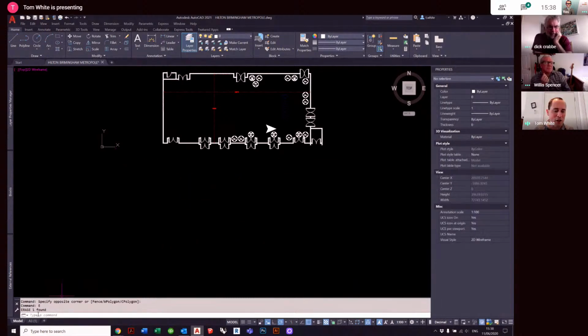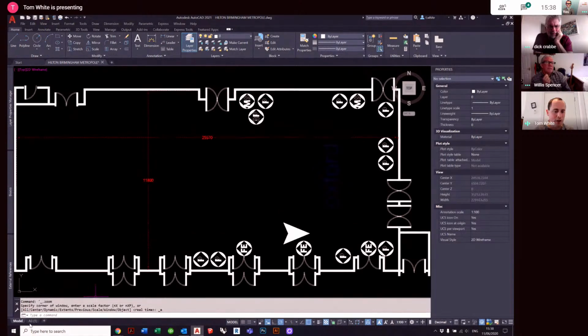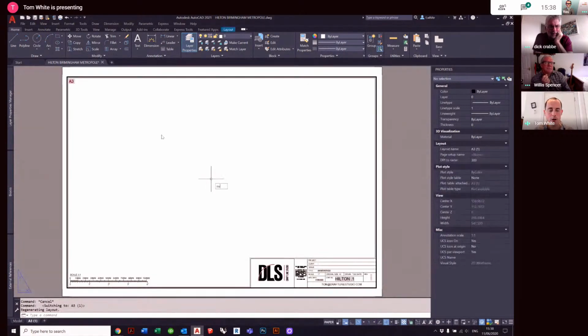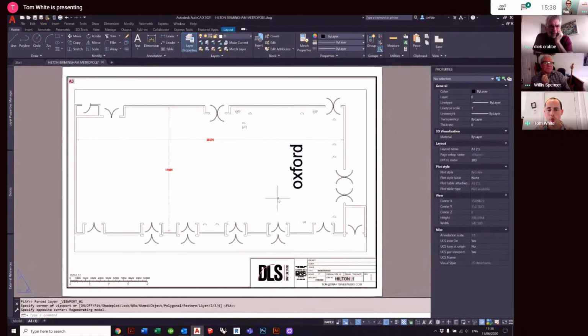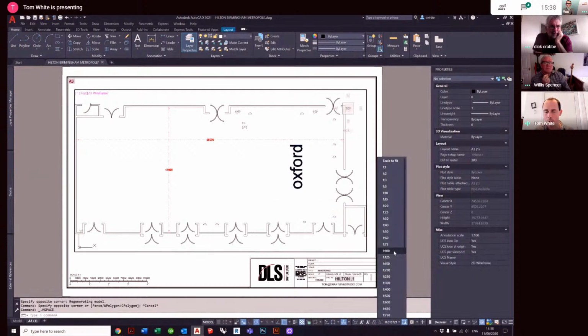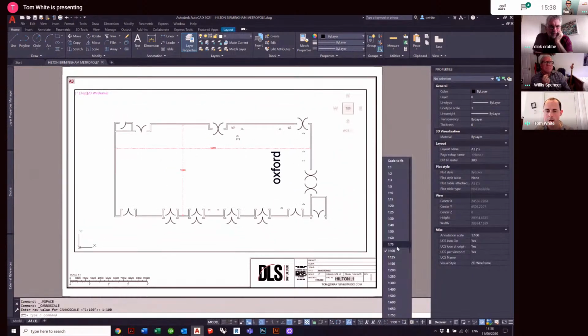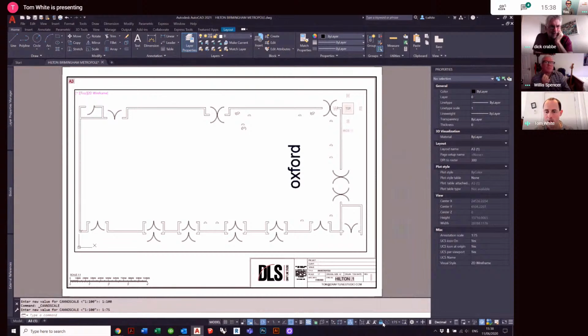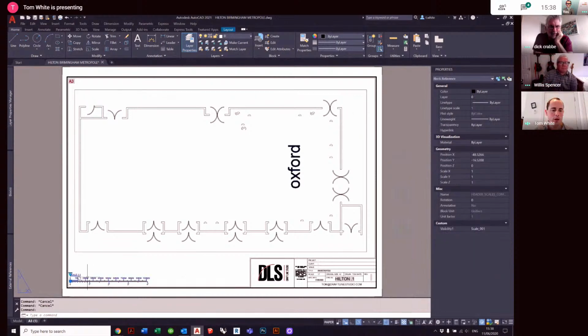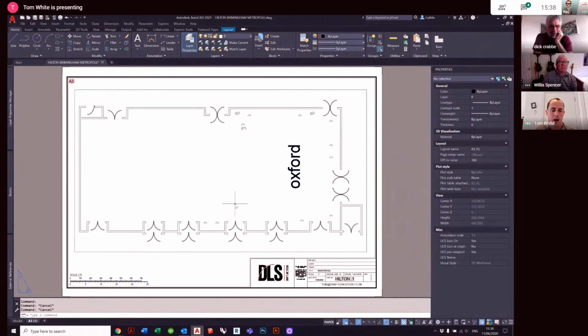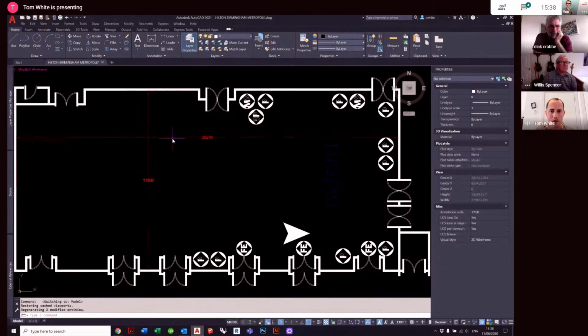Yeah. And so Dom, I don't know if you do it any other ways, but just quickly while I'm doing this, I'm just going to go to the layout space, do a new viewport. I can scale this. I haven't got a clue what scale this is going to be, but 1:75 maybe fits quite nicely. Lock the viewport, always lock the viewport, change the scale line to 1:75. And we now have a drawing which doesn't look amazing because you can see there's a few things missing.